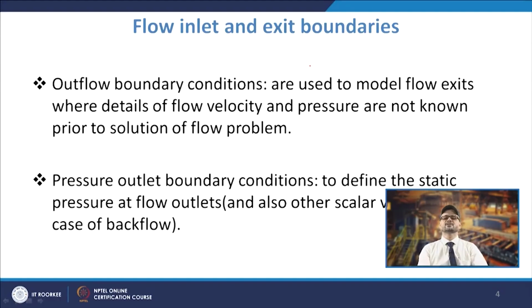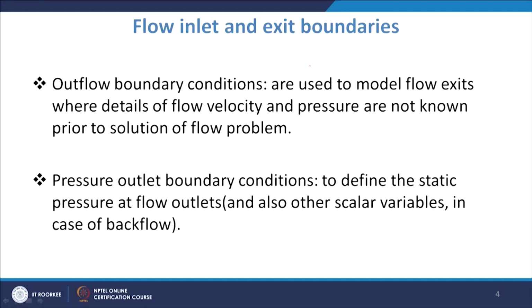Similarly, you have the exit boundary condition, or outflow boundary condition. The outflow boundary conditions are used to model flow exits where details of flow velocity and pressure are not known prior to the solution of the flow problem. In the normal case, when you define the inlet velocity, you do not know what the velocity at the outlet will be.